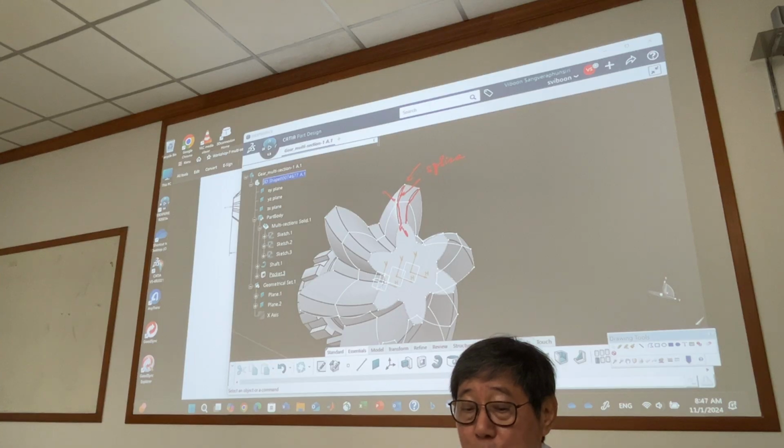If you have only 2 cross sections, you will generate what? A straight line. If you have 2 sections and you want to have a curve, you have to generate this by using a profile or curve, and you use this one as a guideline, guide curve.